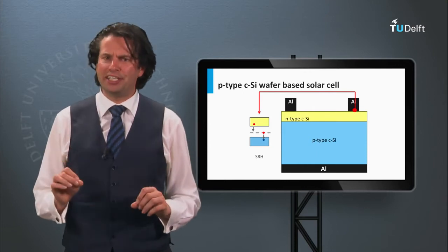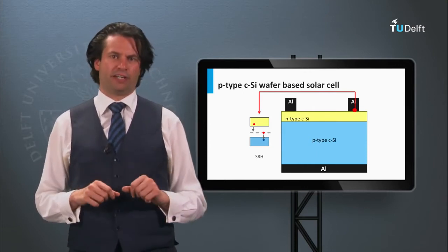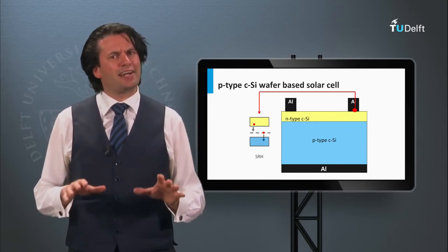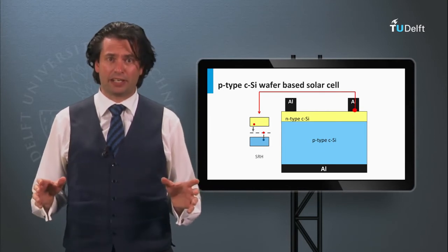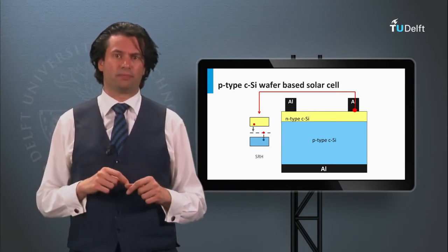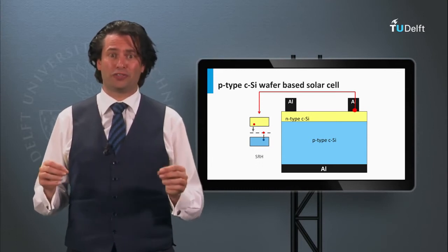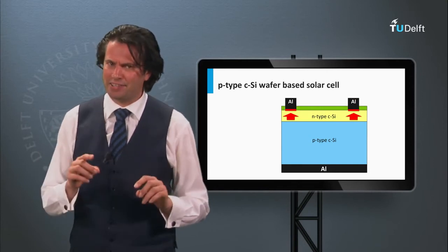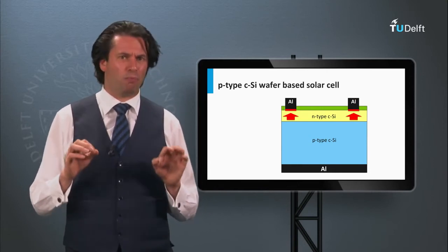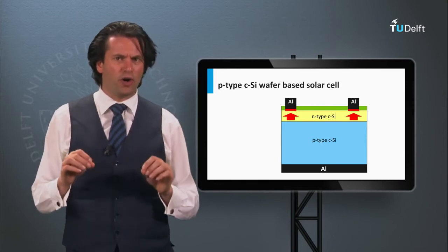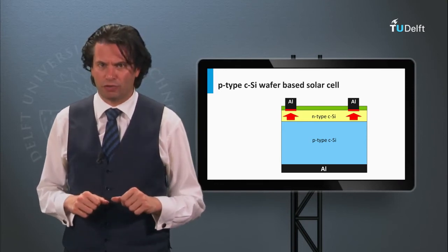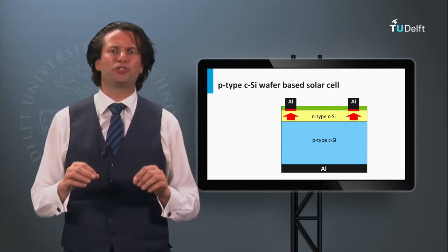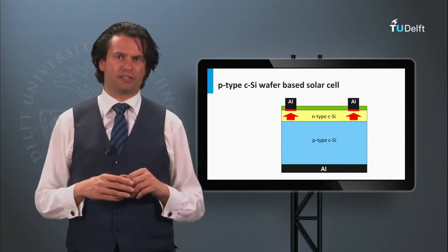Now we look in more detail at the metal-emitter interface. A problem at this metal-emitter interface is that we cannot use an insulating passivation layer like silicon oxide or silicon nitride anymore, as we need electrons to conduct from the semiconductor to the metal. This means that the metal semiconductor interface has more defects and therefore an unwelcome high interface recombination velocity. In addition, a metal semiconductor material induces a barrier for the majority charge carriers.